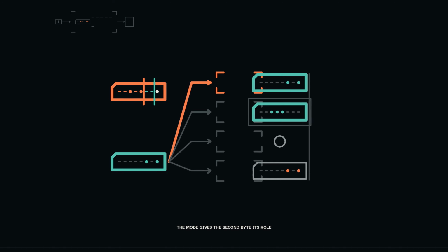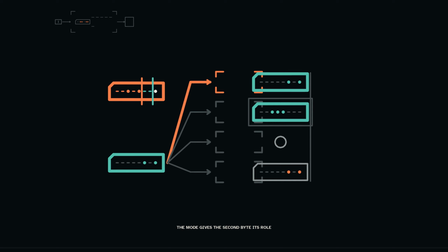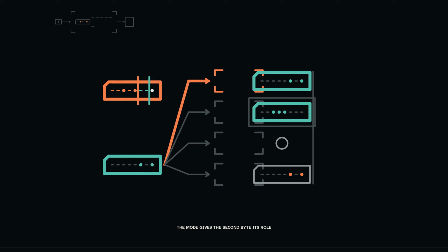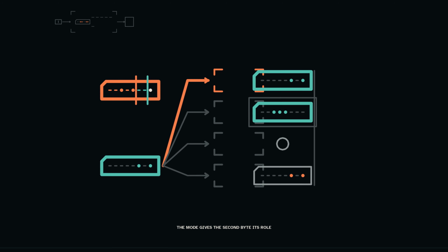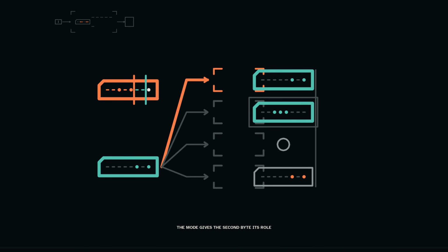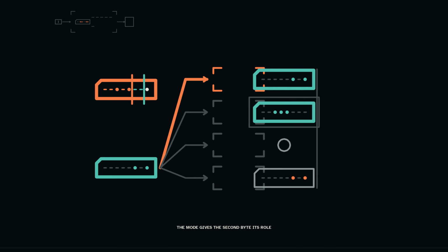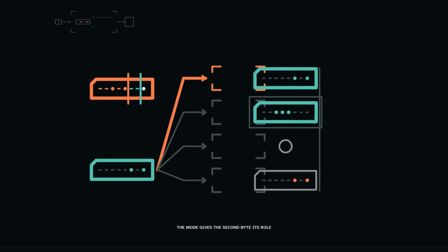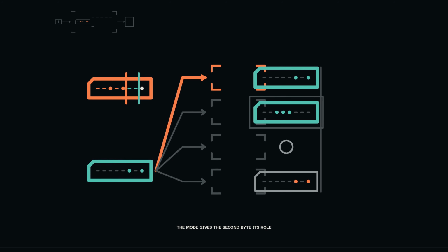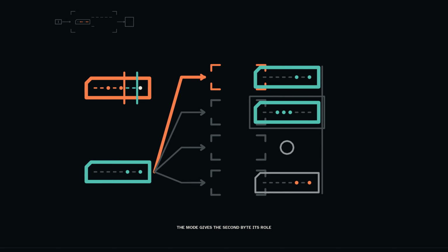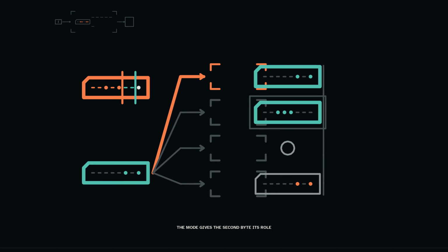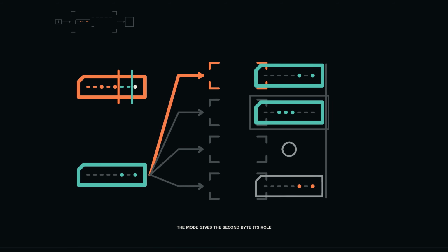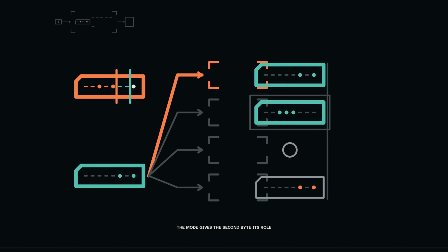The ISA promises architectural results: register values, flags, memory effects, PC behavior, device events, faults, and halting. It need not require every conforming processor to arrange its internal gates exactly like our diagram. The internal organization that fulfills the ISA is the microarchitecture. SE8 freezes one transparent reference sequence so every transfer can be taught and tested. A different implementation could use deeper internal machinery while producing the same declared architectural state for the same program. Contract and mechanism are connected, but they are not the same layer.